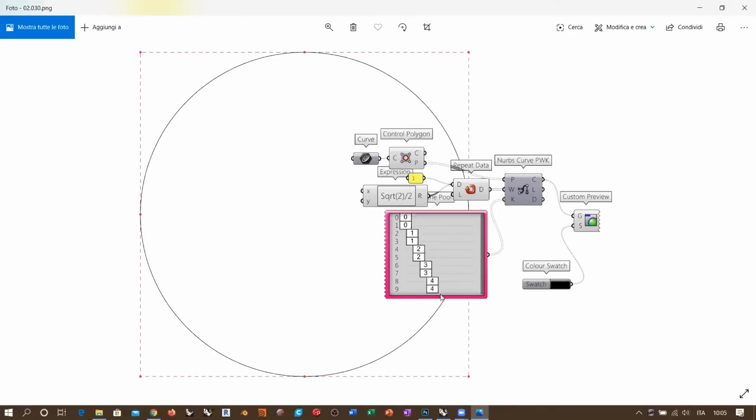And then this is the knot vector, which is a complete set of full multiplicity knots. So this means that you have 1, 2, 3, 4, 5 knots, which means you have 4 spans, and these 4 spans are exactly the 4 arcs that you see here, from this knot to the next knot. And as this is a periodic curve, this full multiplicity knot here actually corresponds to the initial one, because this curve reaches the end point corresponding to the starting point. So the 4th knot span leads to the start point again. So it's a very particular curve, this one.